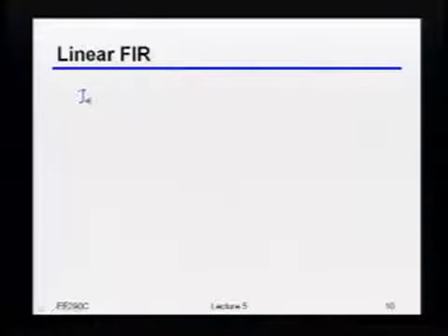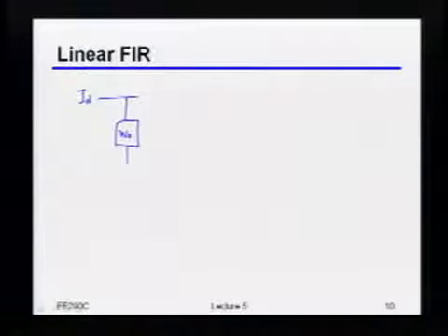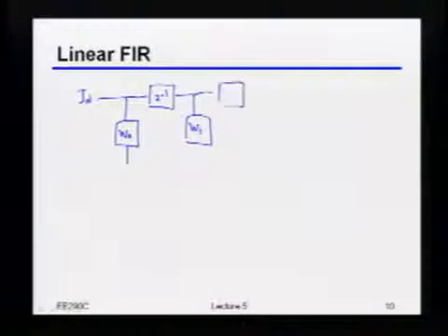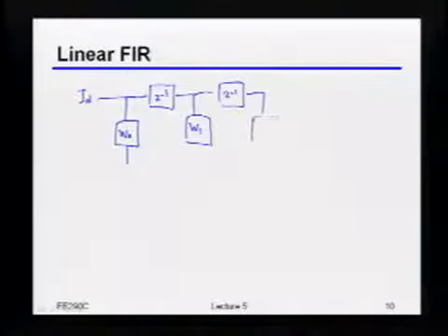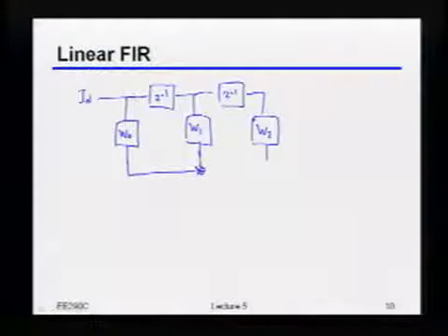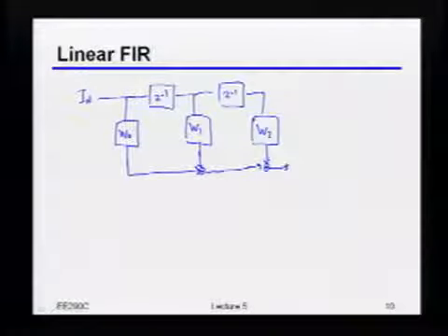Okay? So with an FIR filter, and again, I'm hoping this is kind of a review for everybody, but just in case, I'll quickly draw it. What you're basically doing is working in the discrete time domain. And what you're going to do is take delayed samples of the data, weight them by different coefficients, and then add each one of those samples together. Something that looks kind of like this. And of course, you can keep on extending this to more coefficients like that.